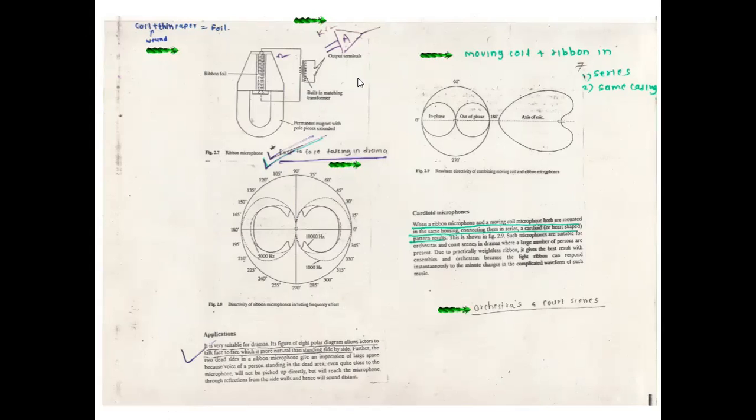Now, one more thing is there in this ribbon type of microphone: the signal which is collected from this foil is very small. That's why a built-in matching transformer is required. Thereafter, amplification is done. This ribbon type of microphone gives you a bidirectional pattern, and a built-in matching